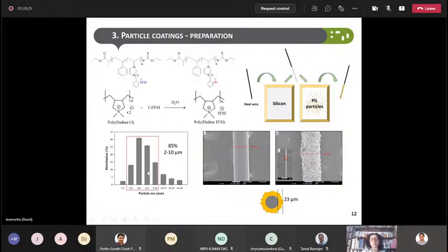And we did not use a molecular sieve. We have very heterogeneous pore sizes and particle sizes, and we really wanted that so that the particles would not clog the surface of the plunger. Here we can see all our particles glued to the plunger. This film has 25 microns of thickness, and it's constituted by particles that are mainly between 2 and 10 microns.